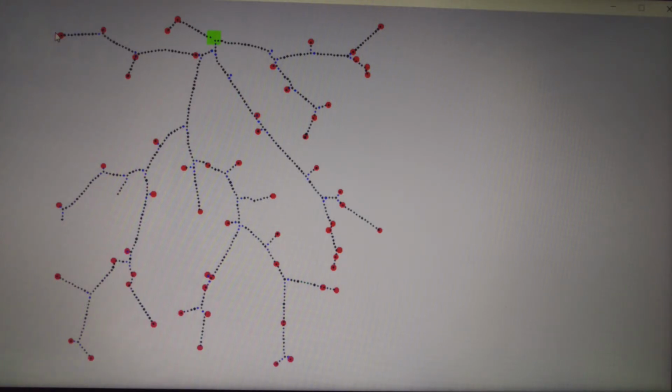Then the process is repeated, starting by reassigning all non-connected wells to the closest line endpoint. Then a line endpoint is chosen at random, and the procedure above repeated. As the lines are built out, you may see some small mid-course corrections due to another line becoming closer to a well than the line in consideration.